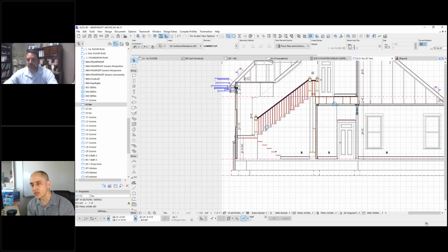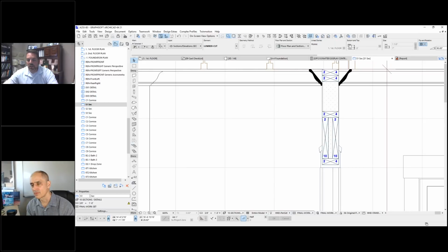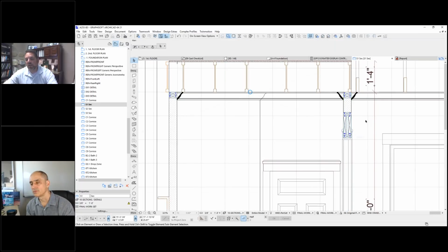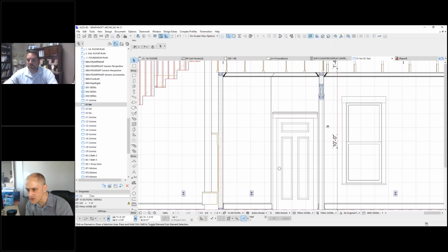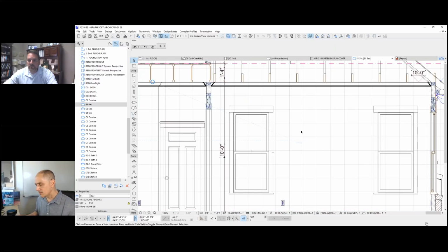Oh, okay. And so your interior walls, are they shown as a composite or as just a simple volume? Yeah, they're a composite, but as a fixed width, but then there's no skins applied. Okay, so you're using the composite tool, but you're setting it as a nominal, the 4-inch thickness, and not showing the actual cladding. Now, I guess we're cutting through an opening, and so we're seeing some casing. Is that the case with the header? Yeah. Mm-hmm. Right. Okay. Excellent. All right.